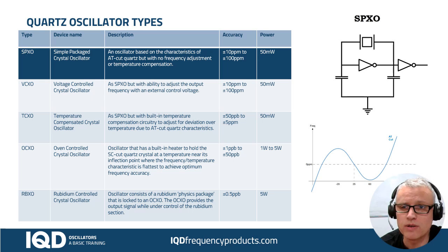The capacitors are used because we're running the crystal in the inductive region of its behavior, and so the capacitors pull the crystal over to the point where the inductance and capacitance cancel each other out, and we're only left with the resistive losses in the circuit.